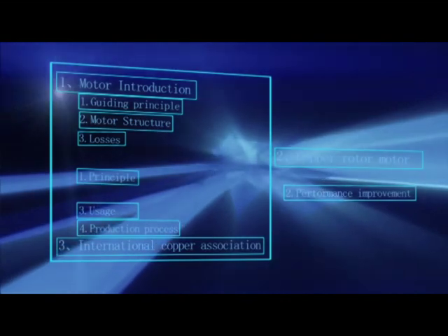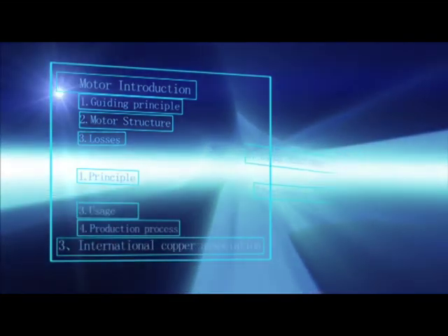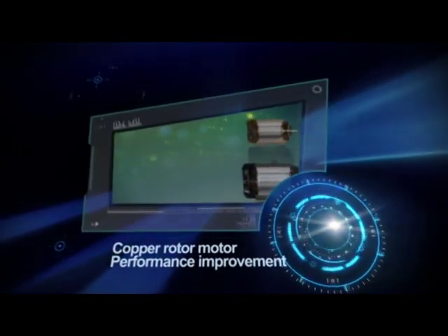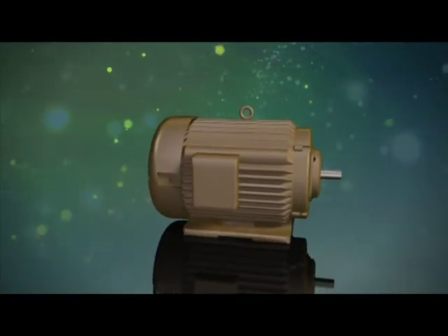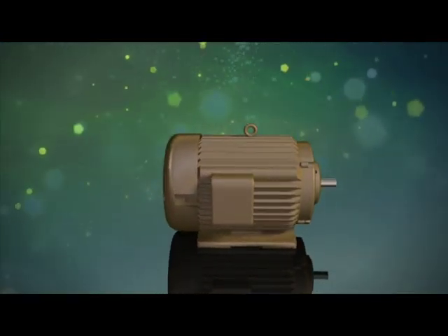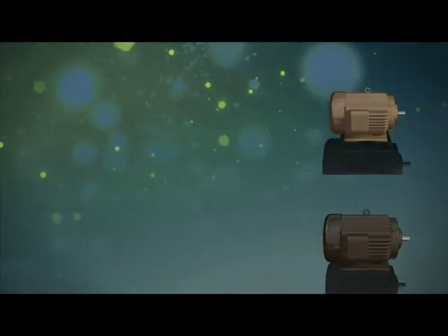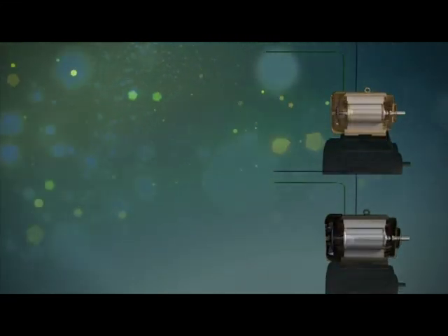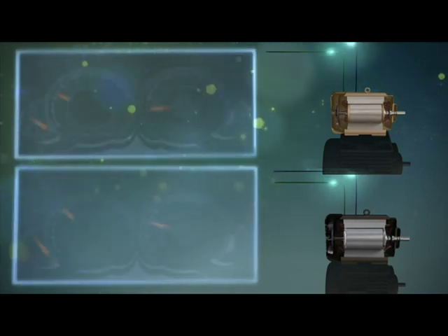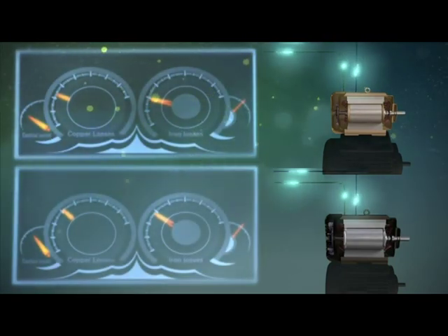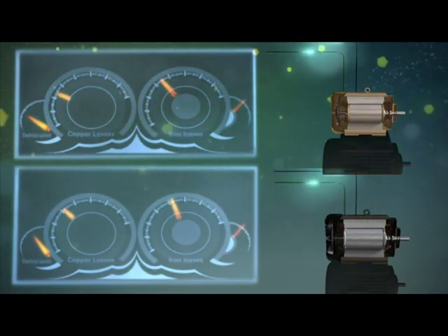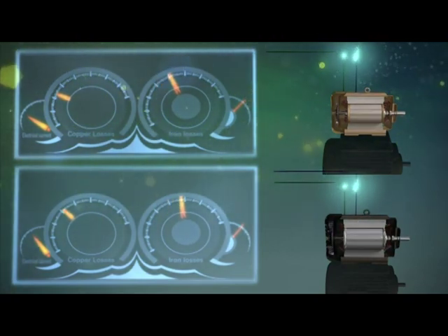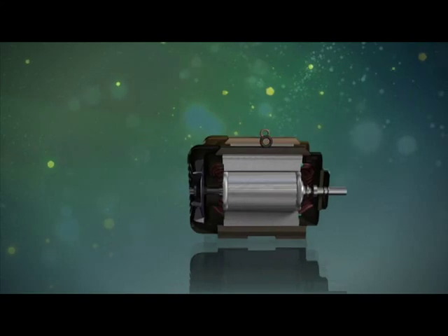Performance improvement. With lowered motor losses, the transfer of thermal energy will be reduced, resulting in lower temperature of the rotor and stator coil. Lower temperature means smaller fans or even no fans need be used at all. In this way, the attrition losses of additional components and air resistance will be reduced to improve motor efficiency.